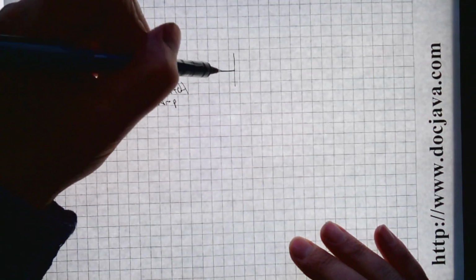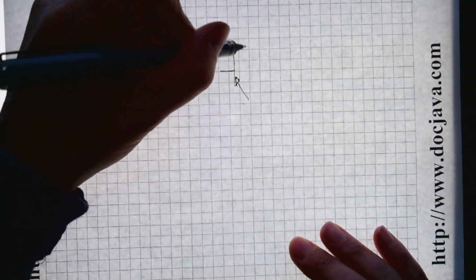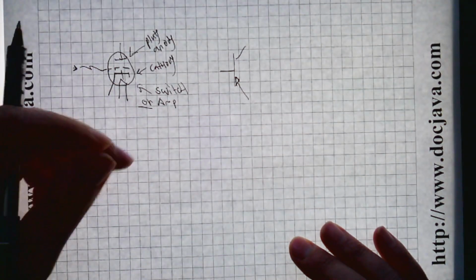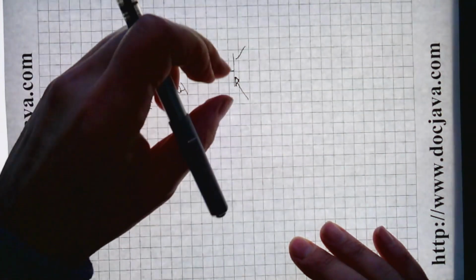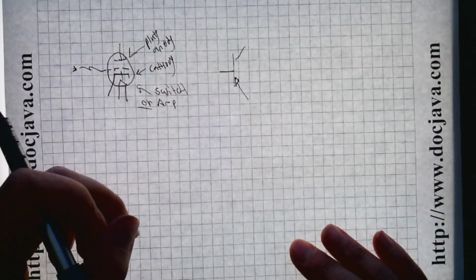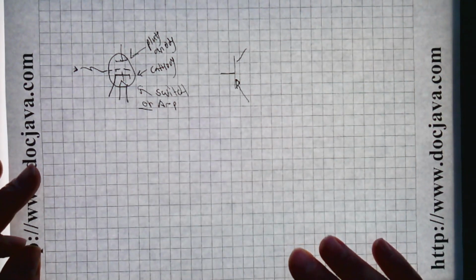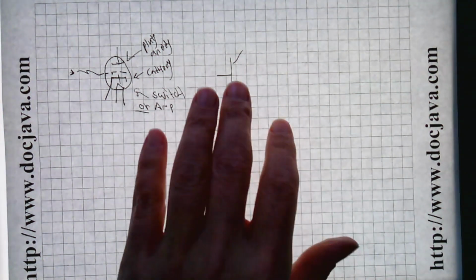Some people make the mistake of saying, well, if I have a bipolar junction transistor, it's just a switch where current comes into the base to allow current to pass from the collector to the emitter. But that's not true. Transistors are actually amplifiers as well as switches. Depends how you use them, and also depends on their specs. So if you drive these things into saturation, they'll work like switches. But if you drive them in a linear mode, they will work like amplifiers.